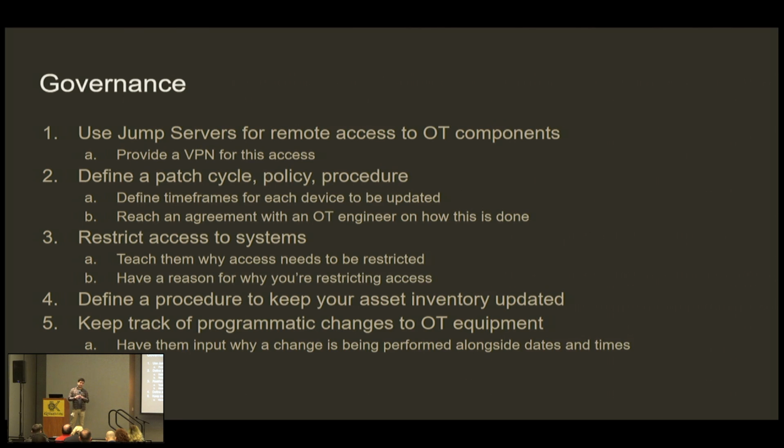And then you'll also need to have governance over your environment after you've started implementing these different processes, right? You're going to need jump servers and VPNs for vendors to access the network so that way they can maintain it. Those vendors are also going to be trying to install different software onto your overall system. So what you're going to need to do is check everything that they're installing, create a list, and then approve different software, or else they'll have software interacting with your PLCs that you're definitely not going to want long term. You're going to have malware and grayware, and similar things such as that.